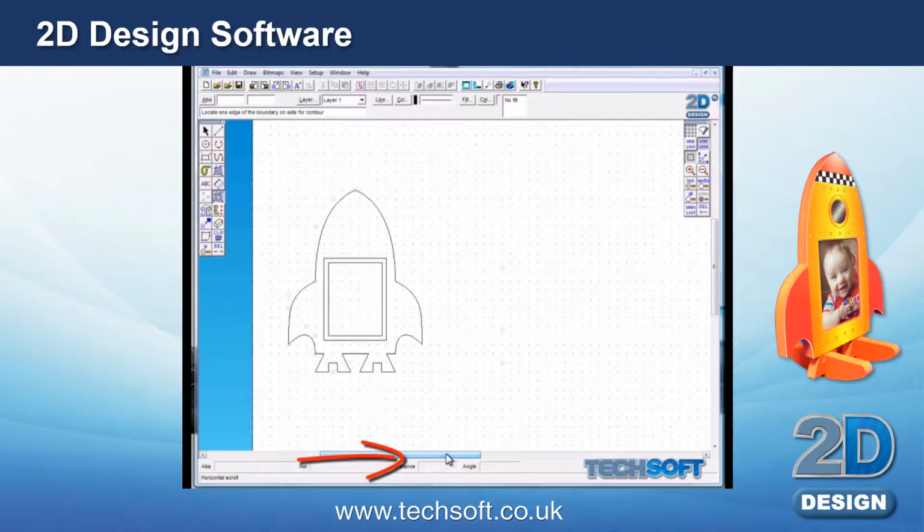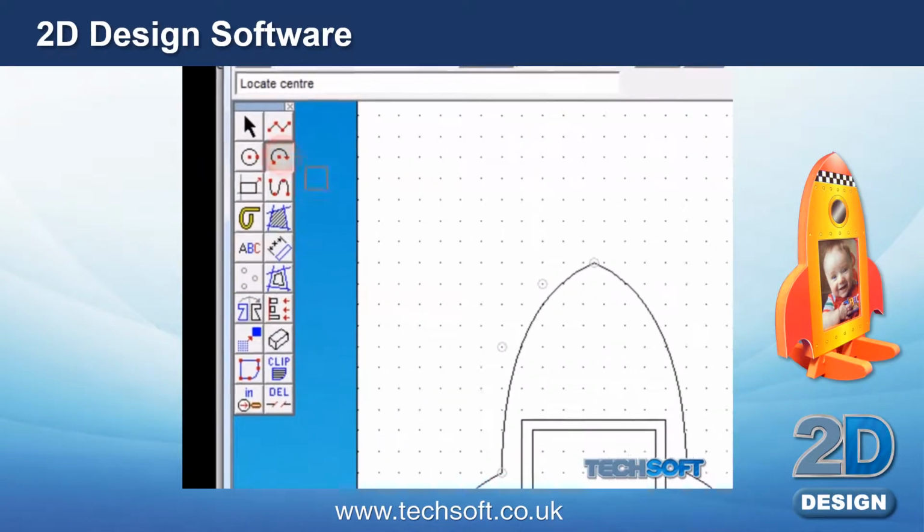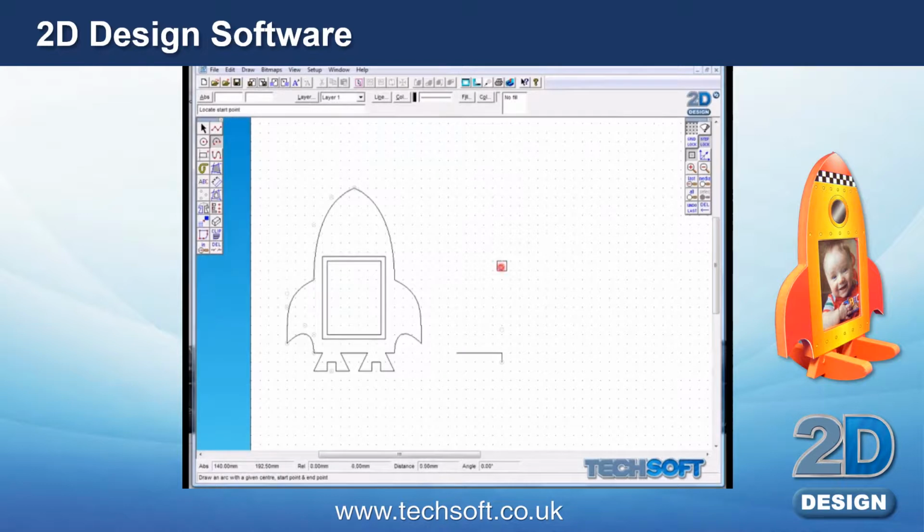If you scroll to the right, you'll notice some more construction points. We're just going to draw the legs here, so we're going to go to series of lines again, using the relative down the bottom, make the leg. Next we're going to use the arc tool. This is just going to get a bit of an arc just so that the stand will allow the photo frame to rock forward and back.